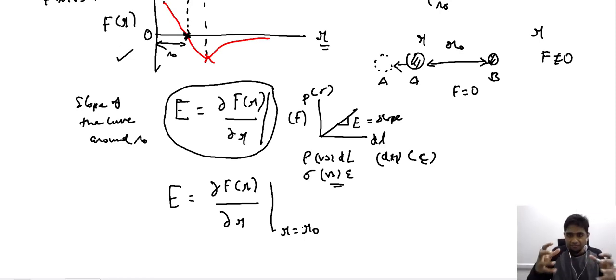When you consider a system like that, you can play around with different alloy combinations, you can bring about different combinations of atoms, or different interactions between the atoms. Now that you have an expression that relates the interatomic interaction, interatomic forces to the Young's modulus, you can create such a configuration that brings about the desired Young's modulus. So from working on the atomistic range, this expression allows you to quantify a parameter that is often associated with